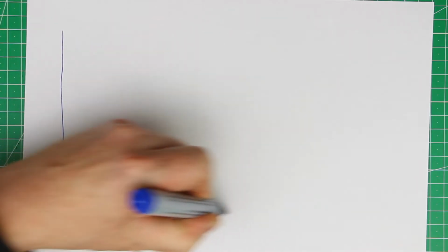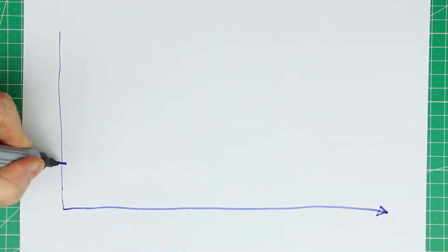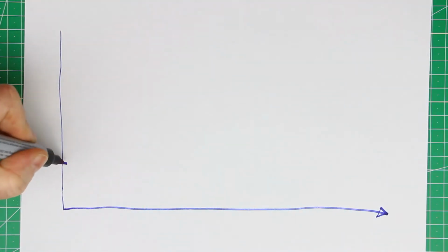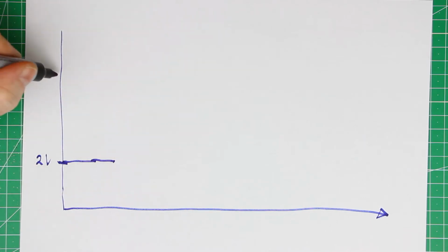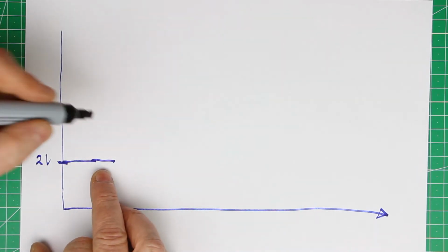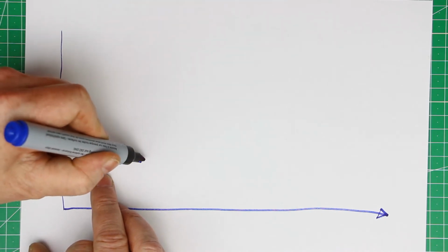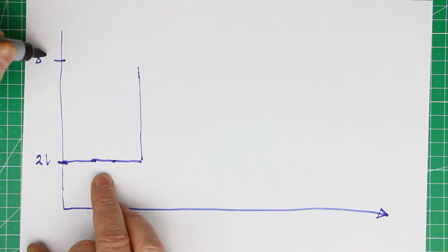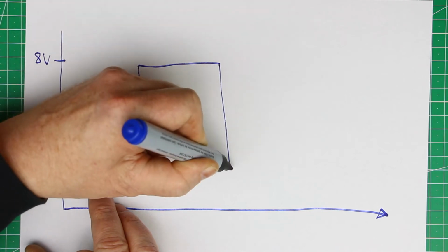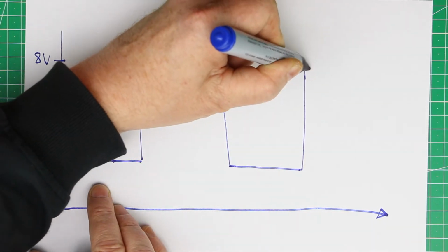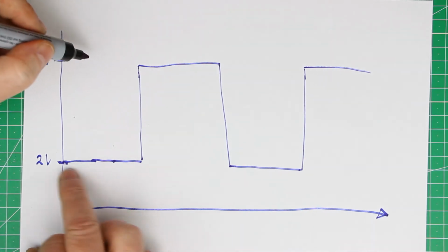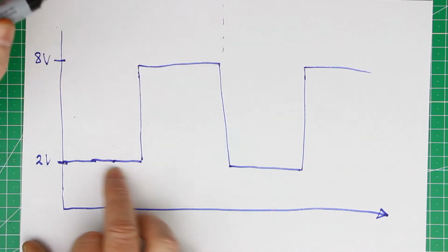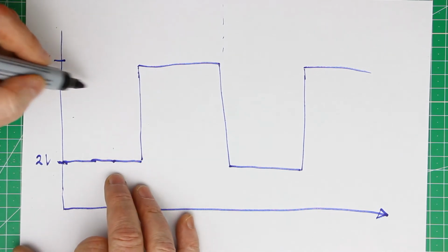So now let's calculate the RMS value of the signal that I fed into the 3 multimeters. Just to solve the secret, I took a square wave with an offset of 2 volts. So let's call it the starting value of the low point of the square wave is 2 volts, and the peak amplitude is 8 volts. And the square wave still is symmetrical. So we just only have to take 2 areas of interest into consideration.